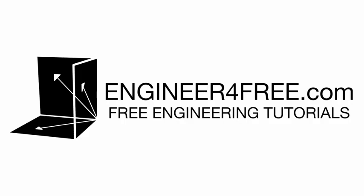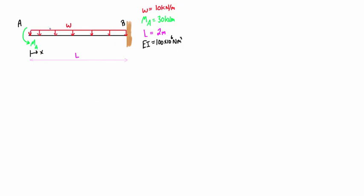Alright guys, welcome back. In this video we want to use Castigliano's theorem to find the deflection at the free end of this beam, and notice there's no point load there, but Castigliano's theorem basically depends on the fact that there's a point load acting at the point that we're looking for the deflection from. So in cases like this where we don't actually have a point load at the point that we're looking for,